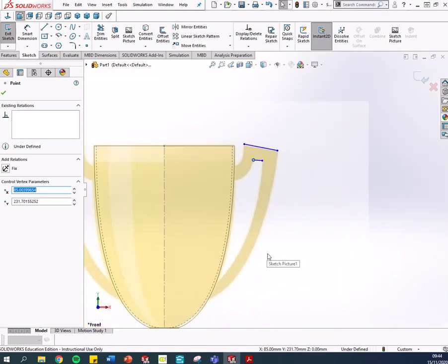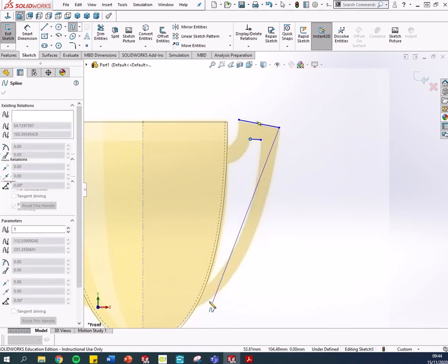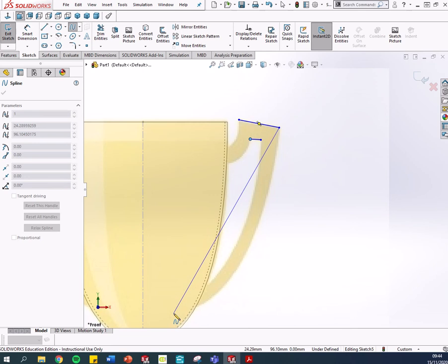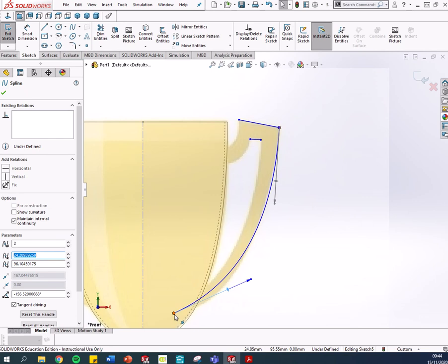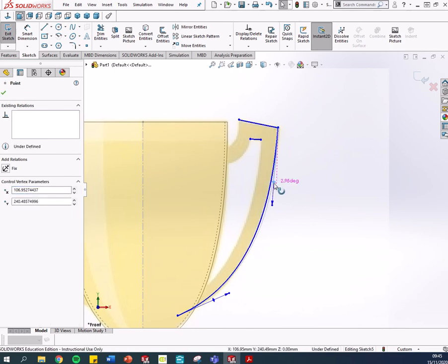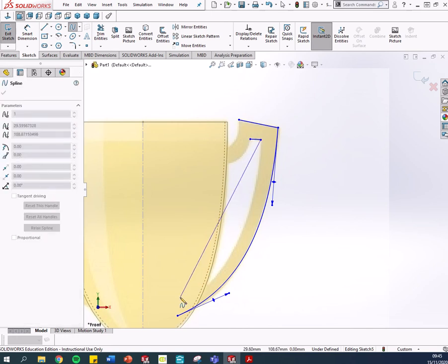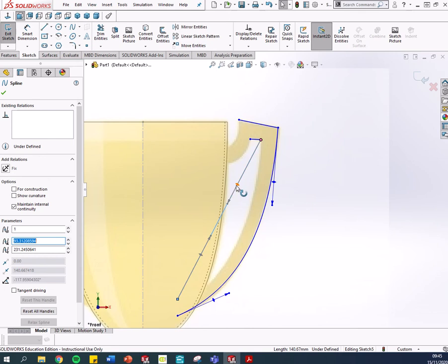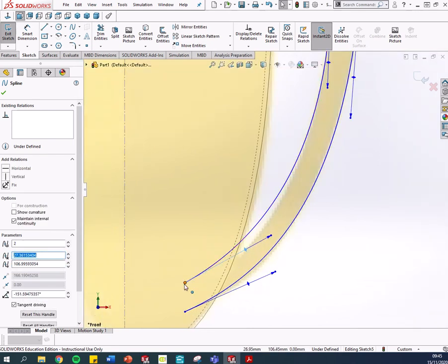And then after that it's just 4 splines. So we're going to trace the whole handle here. So I'm going to start with this big one here, a 2-point spline. What I want to do is I want it to go into the cup. I want it ending inside the cup. Okay, and I'm going to adjust the spline handle now to match. You'll see why I want it to go inside the cup in a second. So that looks about right there. I'll do the inside one now with another 2-point spline ending inside the cup. There we go. Maybe I need to bring this point down.